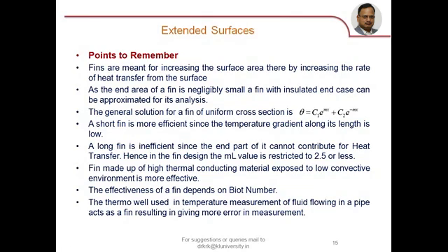Thermowells: to measure the temperature of a gas flowing inside a pipe, we construct a small well into which we insert the thermometer. That well in which we insert the thermometer, and which is in turn exposed to the flowing gas, is known as a thermowell. The thermowell used in temperature measurement of fluid flowing in a pipe acts as a fin, resulting in more error in measurement.